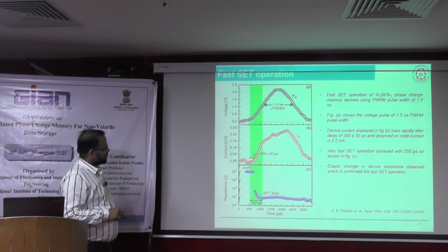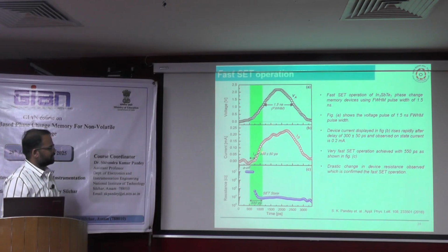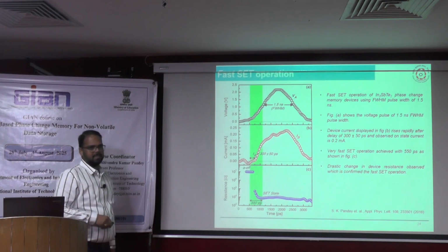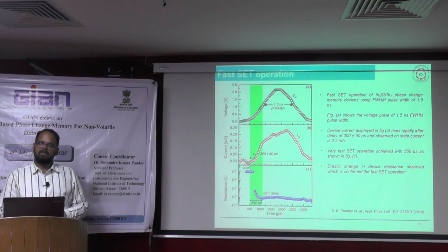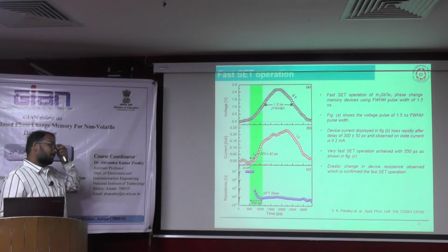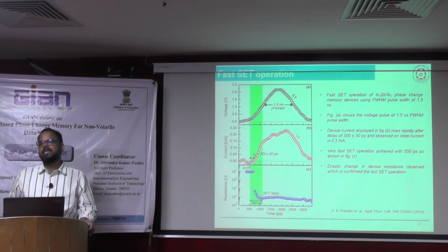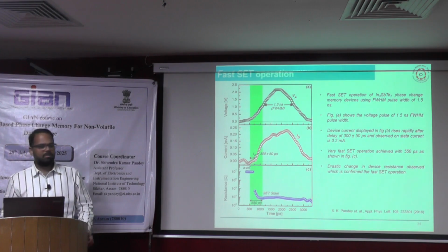So we have seen here the shortest delay time, which matches with earlier reported things, around 300 picosecond, and that material is switched from high resistance amorphous to fully set state. The time duration is around 500 picosecond. It is very less as compared to earlier reported value, and it is comparable with well-known material. But the interesting aspect is that you are getting a large resistance contrast, which is easily comparable.